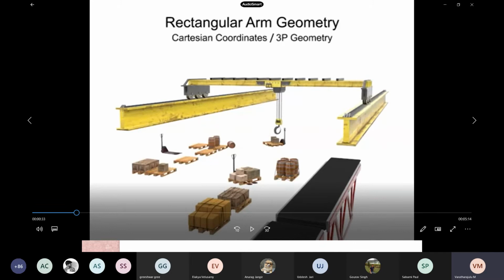And I'll remind you of these points related to the other pairs also. The revolute pair permits relative motion about a unique pair axis and has a single degree of freedom. The prismatic pair permits relative sliding parallel to a unique pair axis. The cylindrical pair permits independent relative rotation about, and relative sliding parallel to, the pair axis. This is what we have given with some slides. The spherical pair also we have detailed. And please remember this 3P with those pairs.